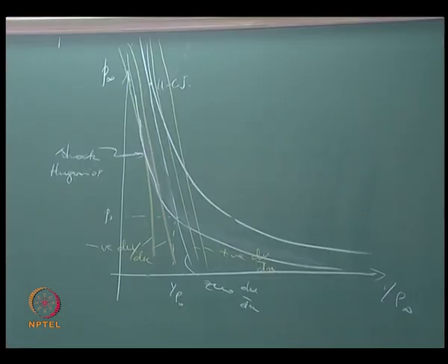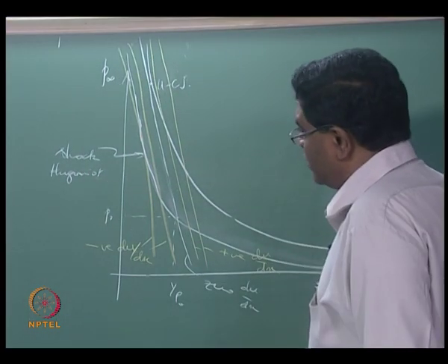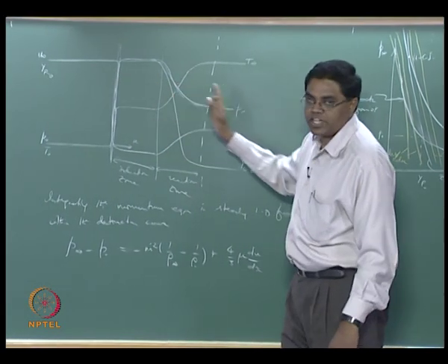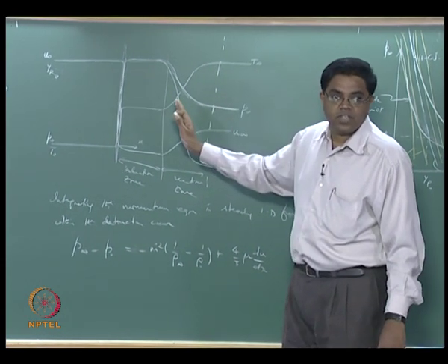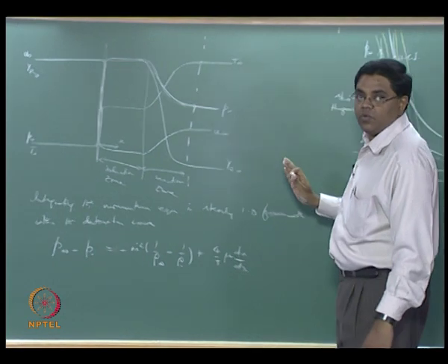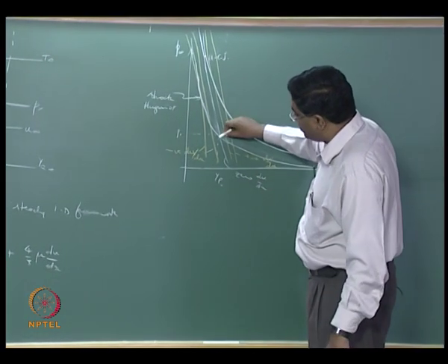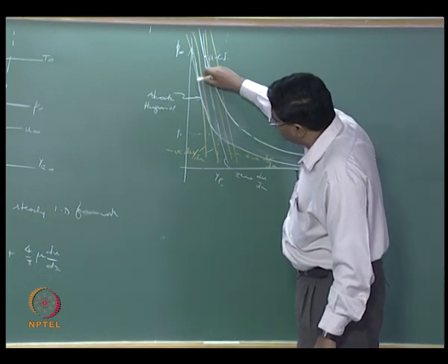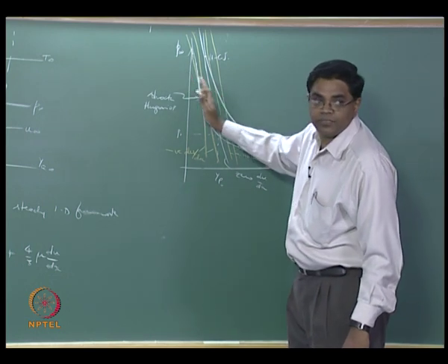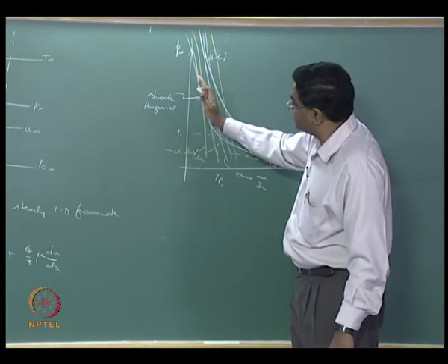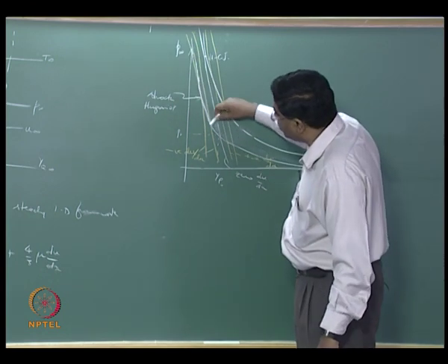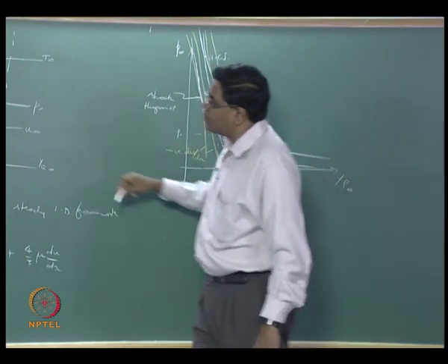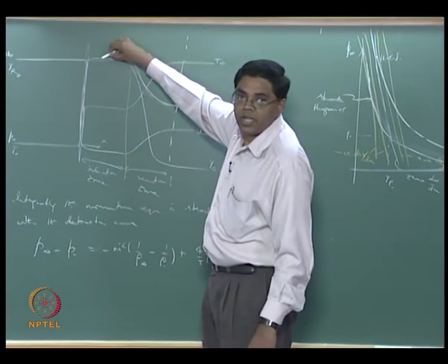Okay, so if you strictly follow the idea of having a shock followed by reactions, and the heat release is happening only in the reactions, what it basically means is you rapidly go from the origin through a set of negative du by dx Rayleigh lines along the shock Hugoniot, as rapidly as you can, up to the peak pressure, and I told you I'll talk about this.